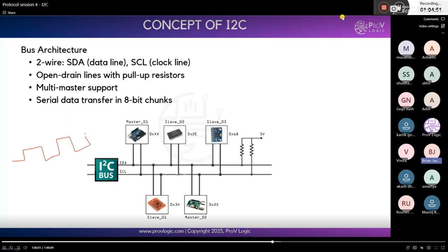Okay. So whenever the clock is high constantly, SDA must go high to low. When both match, we can initiate the transfer. Whenever the clock is constantly high and SDA goes low to high, in this case we can stop. We will write the program according to that.